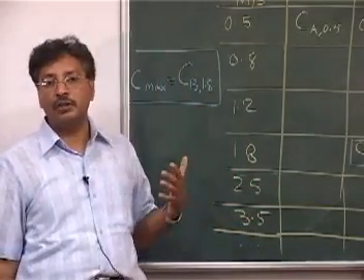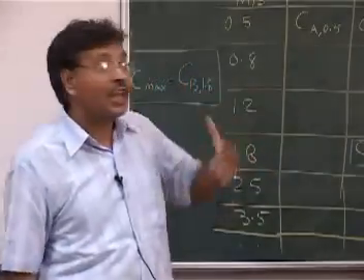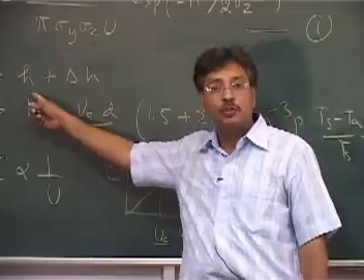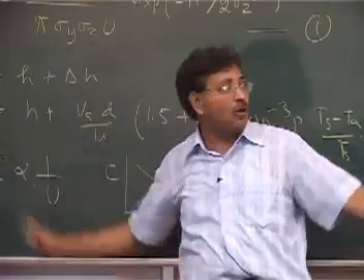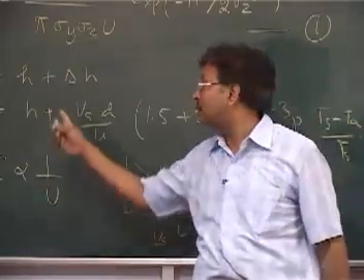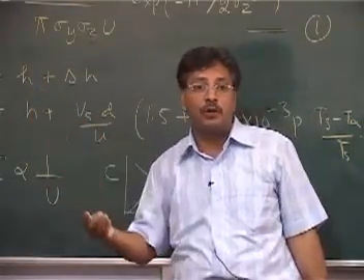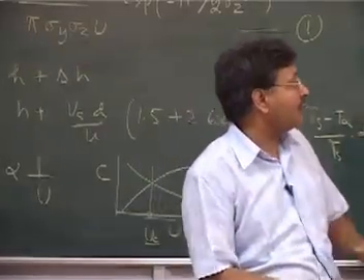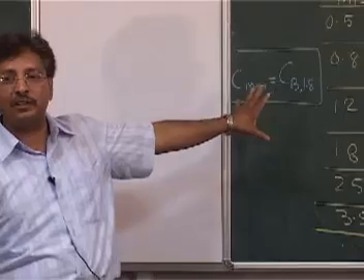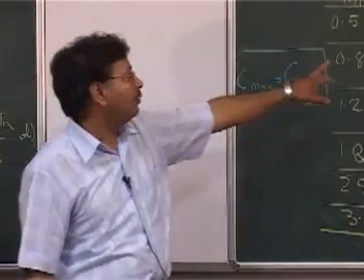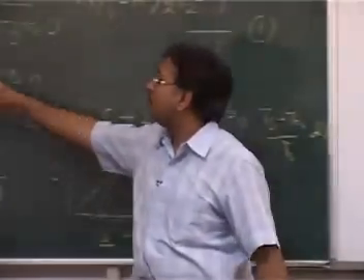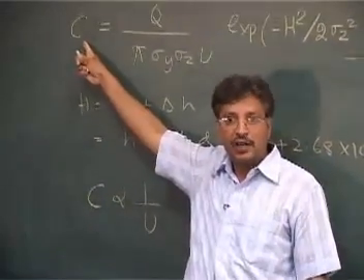Suppose you are designing the pollution control, or you are designing a stack height, let us say, you can even go back and do all the calculation to find out what should be the physical stack height, isn't it? If you know the maximum allowable concentration is like this, then you can do the inverse problem and find out the H, right, which we people do. People say my maximum concentration should not exceed 100 micrograms. Then you say, all right, the worst ever is 100. Then whatever the wind speed and wind direction, you can go and find out the H by putting the worst maximum concentration here, right?